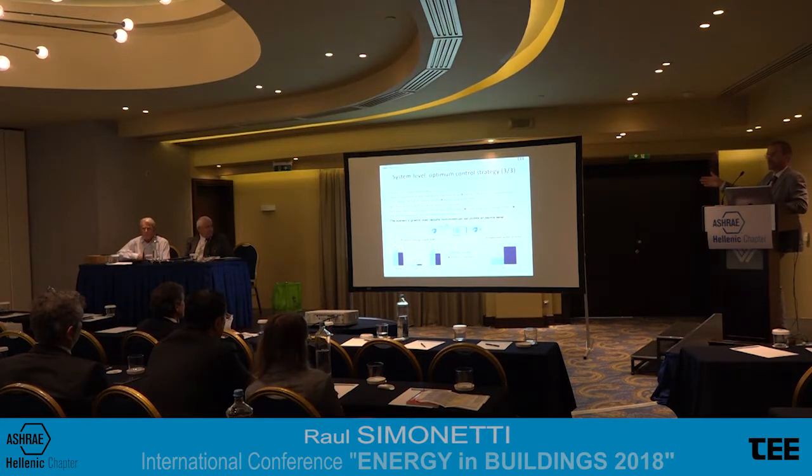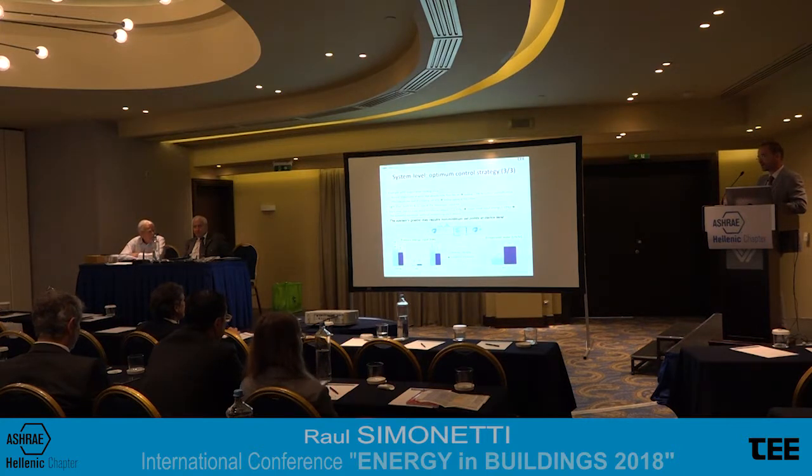Now, both can run at their minimum duty, the evaporative cooler for the minimum level of humidity, and the cooling coil for the minimum level of cooling, in order to respect both the set points of temperature and humidity. However, since the evaporative cooling can also do cooling, you can exploit the tolerance on the humidity set point in order to add a bit more humidity, while still respecting the tolerances, and cooling at the same time, so that you can reduce the duty of the cooling coil and save energy at the chiller. You can see it from these charts at the bottom.